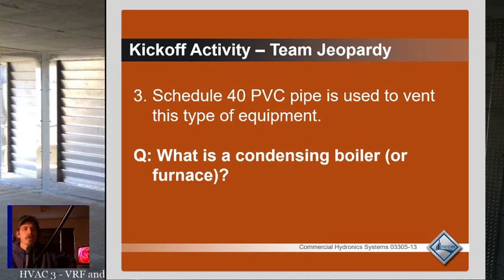So if you're running your boiler at 180 degrees, the flue temperatures are always going to be right on the verge, right on the edge of being too hot for the PVC. So all you need is some kind of issue where the water overheats a little bit, and you're going to end up with an issue where your flue temperatures go up, and now the PVC is all but melting, okay?